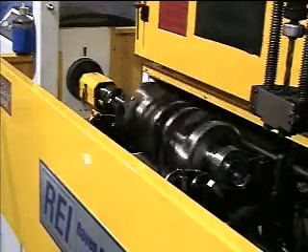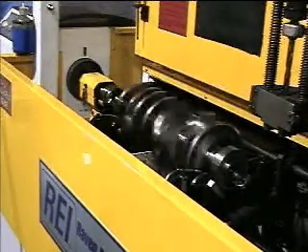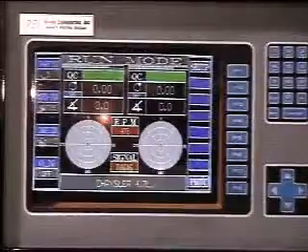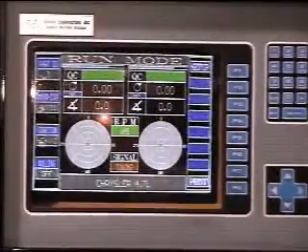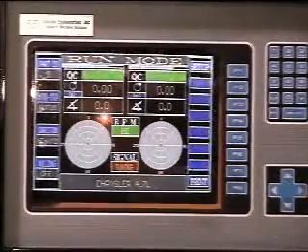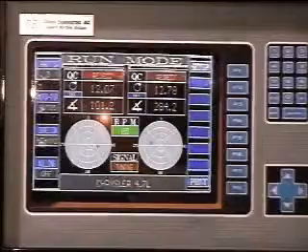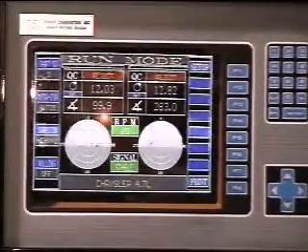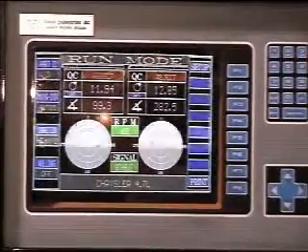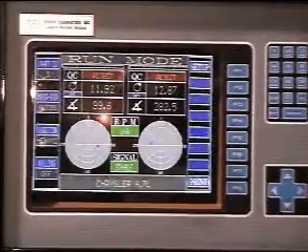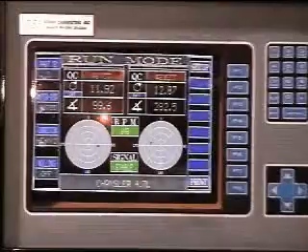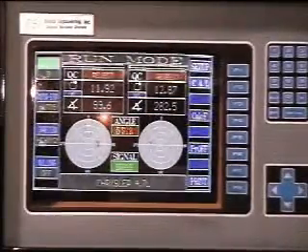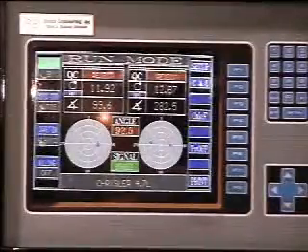Typical production cycle is as follows. After loading a production part with the bob weights, if required, into the cradle and coupling the part via end drive or belt drive, the initial audit is started. The audit is automatically stopped by the indication system. Upon completion of the audit, the correction information is indicated on the screen.